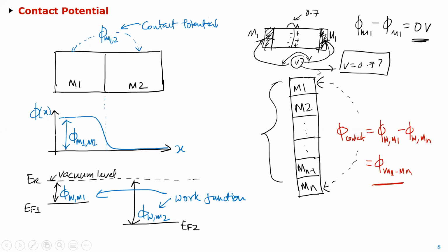So if you just take a diode and put this, the contact potentials will cancel and you're just going to measure the contact potential of the two metals. So obviously when you put it inside a semiconductor device, that's why you don't do M1, M1. You have to always dope it with some P plus or N plus before you actually make a contact. That's one of the reasons you do that. Okay, makes sense? Any questions on that?